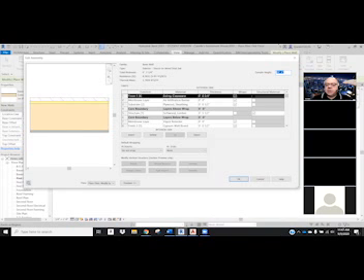So a structure is the lumber. That's the strength of the wall. And we already have that set to 2x6, so we're good to go there. 5.5 inches tells me it's a 2x6 stud wall. That means the distance across is 5.5 inches. But a substrate is like plywood, or something like, trying to think, a ledger board. It might be a sill plate, something that's just a support, not really adding strength, but supporting the strength of the wall.